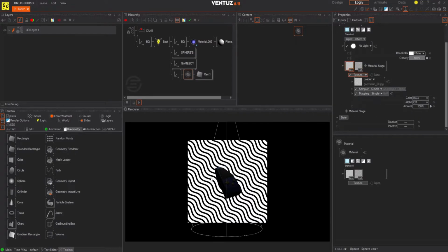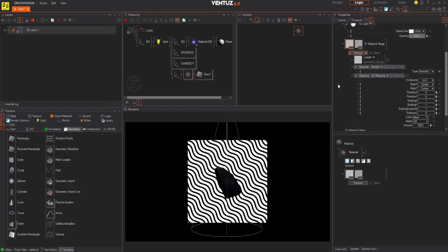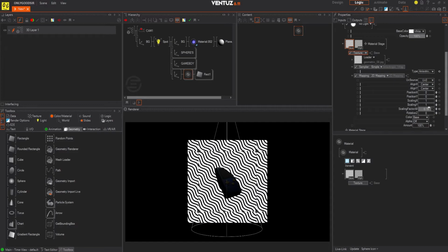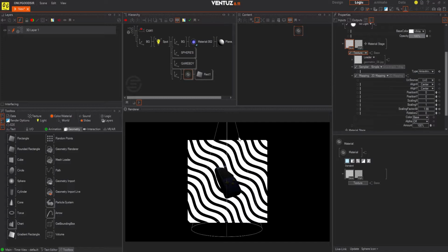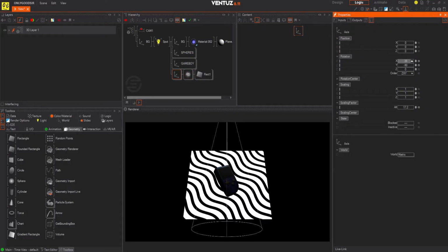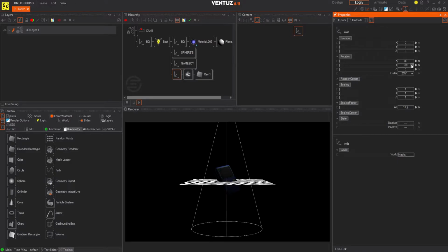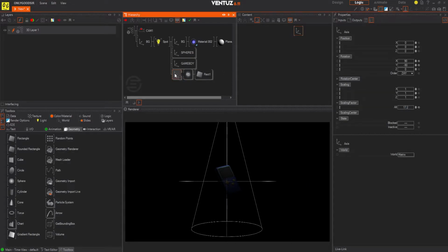So now when I change the base UV mapping, so I'm going to the UV 0 and change that clamp to wrap, anything I do on the base will change the alpha underneath. So as you can see now, I can scale this up and down, and see the wavy lines. So what I'm going to do is just rotate this and make this point upwards, so 90 degrees up. And if I turn the bounding box on, we can still see that's the plane, and I'll just call this shadow. This is what projects our shadow.